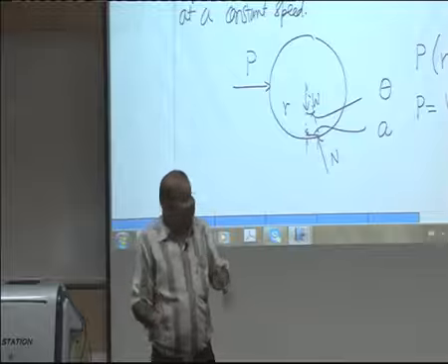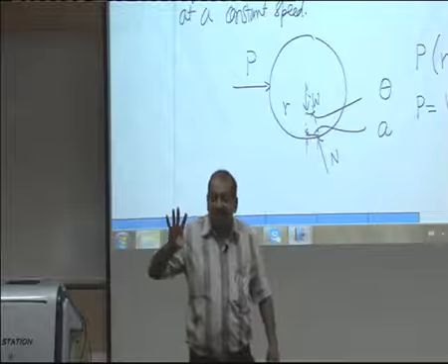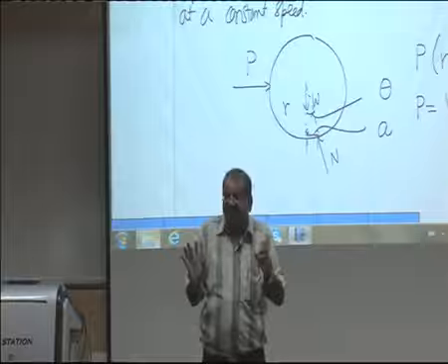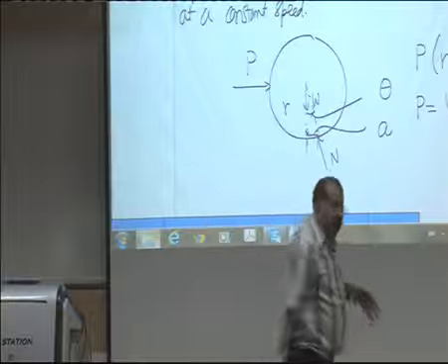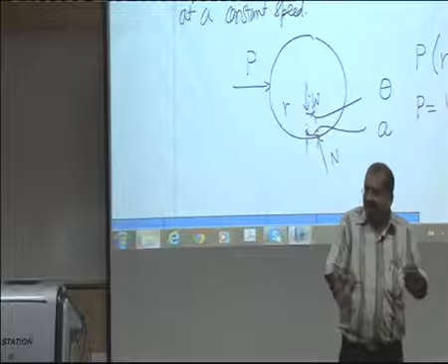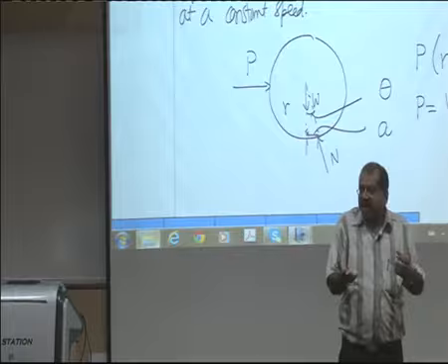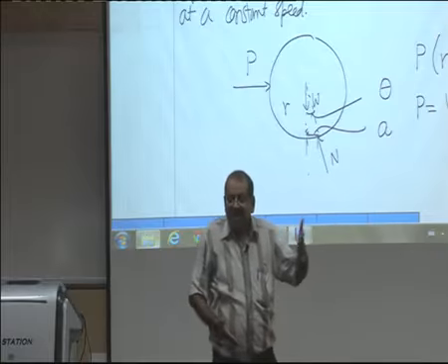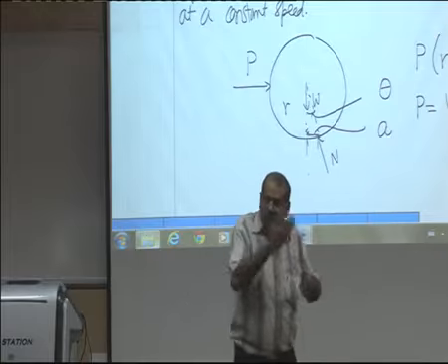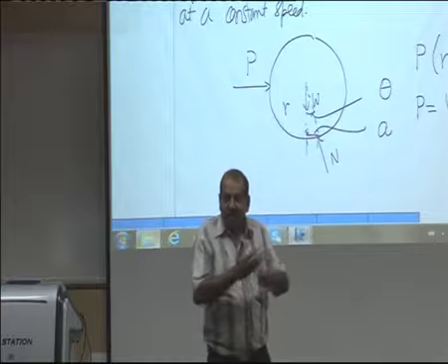So that means a/R is effectively a coefficient of friction when the body is rolling. In the ideal rolling case, we assume that there is no friction, it's acting just at the center point. But actually this is one level ahead of approximation, where in rolling also you will have a slight friction, which is given as a/R.